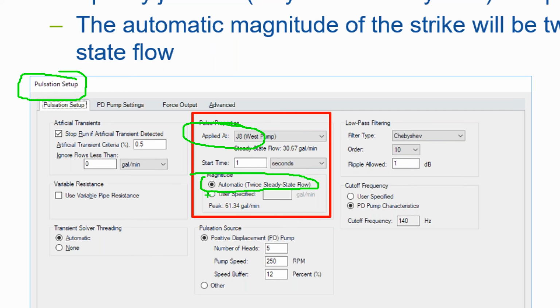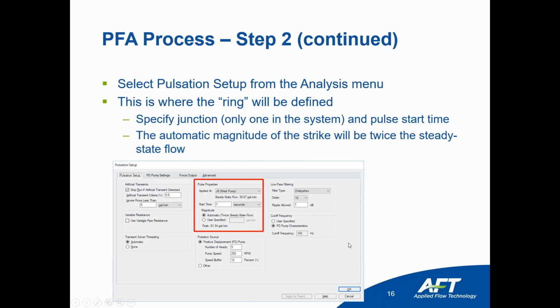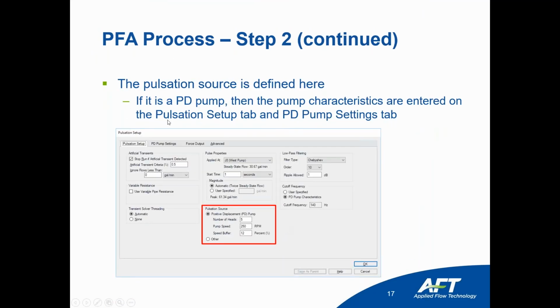So in step 2, we're going to ring the system. A common test for mechanical vibration and natural frequency measurements consists in striking the pipes with a short hammer blow. An ideal impact is a perfect impulse, which has an infinitely small duration, causing a constant amplitude in the frequency domain. This would result in all the modes of vibration being excited with equal energy. So again, you cannot hit it too hard. You cannot hit it too soft. So it has to be an ideal impact.